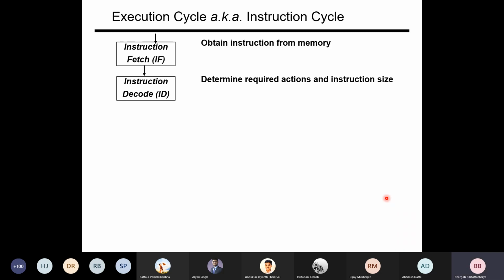So I need to enable the decoder circuit, which is built in hardware. That would extract the corresponding bits from the instruction, the opcode field, maybe the first six bits or 8 bits or whatever, depending on the architecture, the format of the instruction set, and we decode those bits, and then you determine what kind of instruction it is.